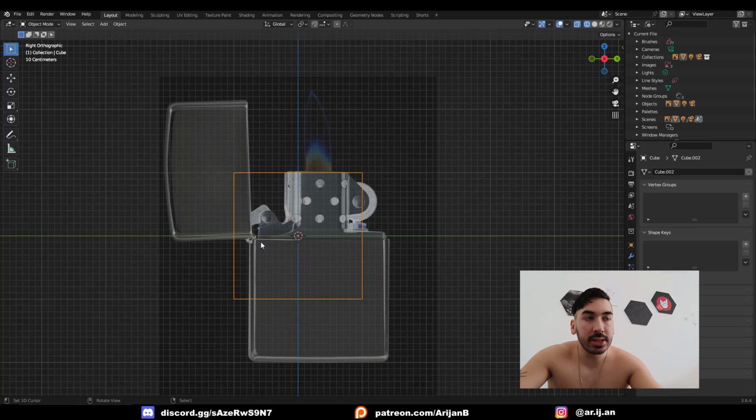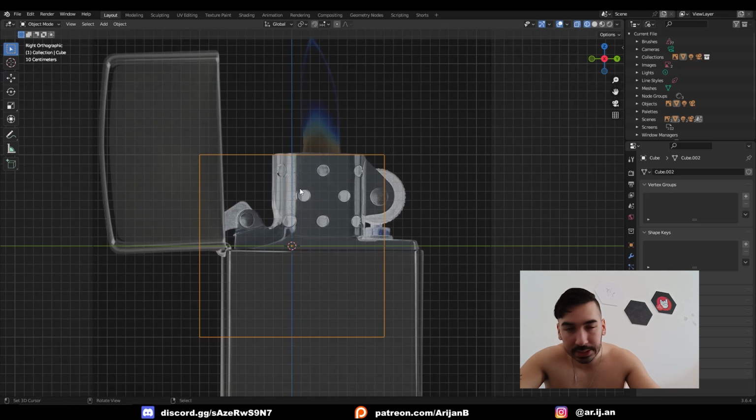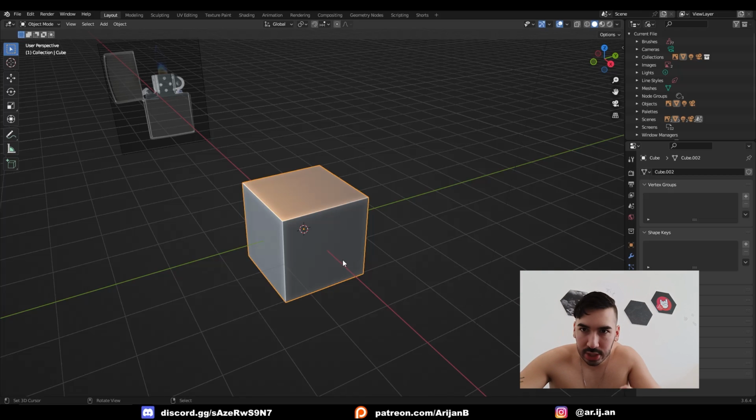If you start by creating the low poly part, you're gonna have to add a lot of geometry afterwards, you're gonna have to subdivide, and that's very likely to give you trouble, so you always wanna avoid that if you can. I'm gonna start by making the top part here where you have this neck with the holes in it. When I do this, I'm also gonna try to follow the grid, just because that way I can snap stuff and it's gonna be a little bit more under control.